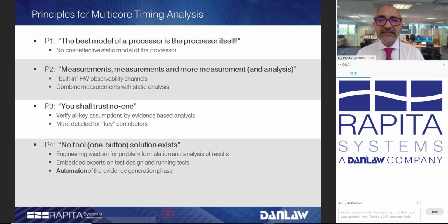Some chip manufacturers build in tracing ports and debug interfaces to collect some of that data, but others don't. So we have to provide alternative mechanisms, and as part of the hardware requirements specification, make sure that observability is possible.